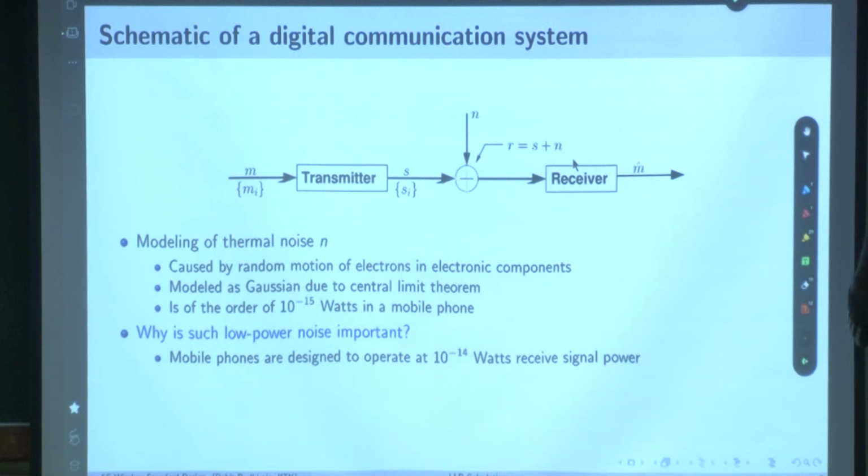By the time it reaches the base station, its signal strength would have deteriorated that much. So depending on the distance, the signal power is becoming close to the noise power. At this signal power, that is only 10 times stronger than the noise power. So now the noise is becoming relevant, right? So you have to consider this. That's where this AWGN channel comes into the picture.